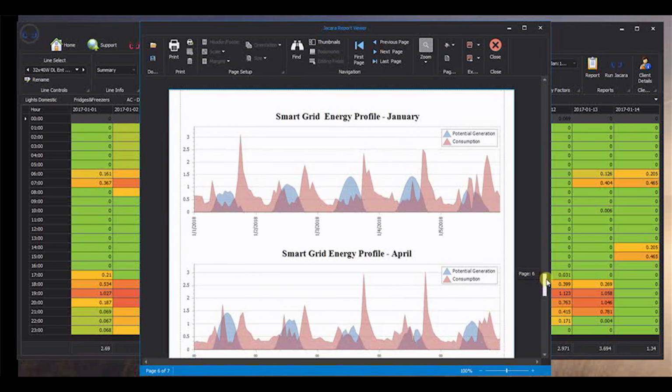I don't believe that changing the panels to east or west, if we can find an east facing roof or a west facing roof, in this case it's not going to make much of a difference. So we can't find a profile where every day in the afternoon we're just missing it. If you look at it, the evening consumption seems to be more towards the evening, and facing it west isn't going to help us much, even in Cape Town. I think the consumption is too late in the day.